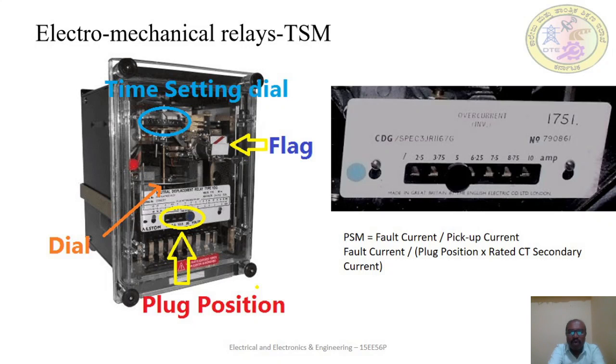These changes in one or more quantities signal the fault, their presence, their location and type, and the protective relays have detected the fault. The relay operates to close the trip circuit of the breaker, which will open the circuit breaker and disconnect the faulty circuit. The above figure shows the electromechanical relay. There are some fundamental requirements for relays, like sensitivity, speed, selectivity, reliability, simplicity and economy.